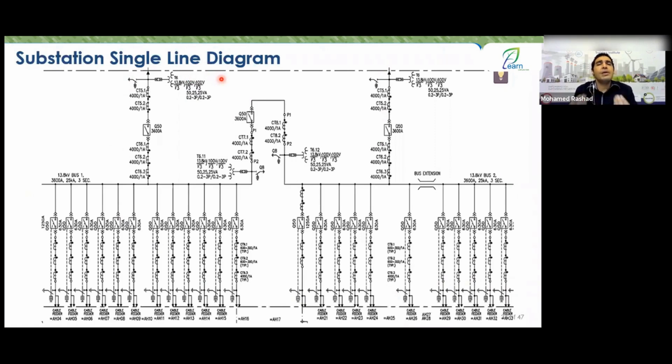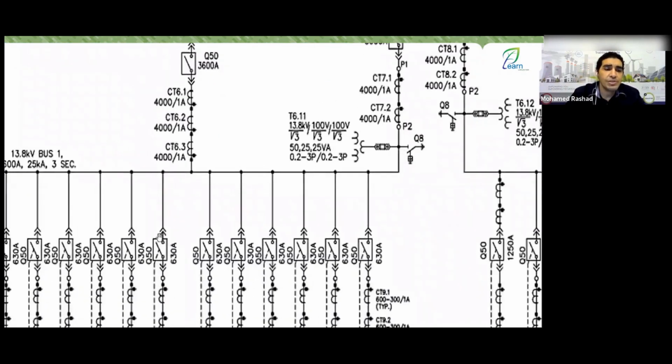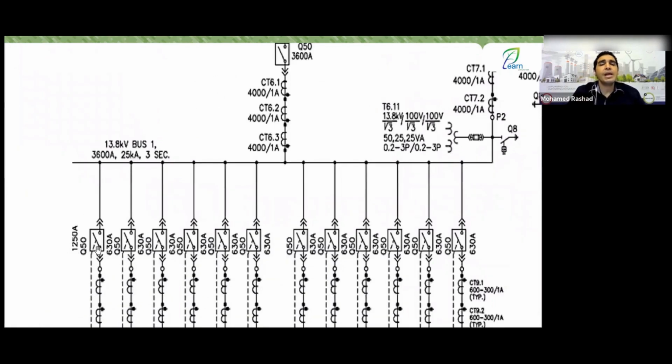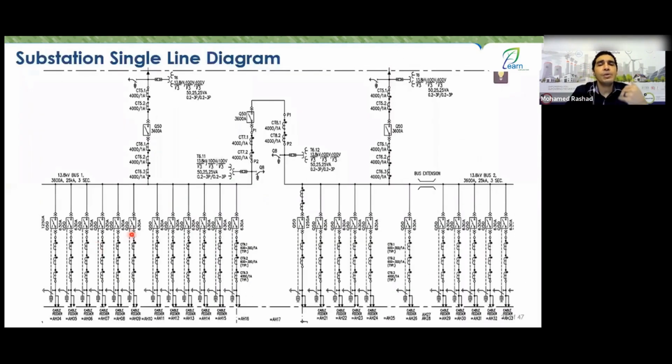And it's called a single line because our electricity, whether in generation, transmission, distribution, or even at your home, is three-phase. So you always see a bus bar as a single phase, you always see a breaker as a single phase, but in reality, it's three-phase. So here we call it a single line diagram, meaning I draw one line for you, any phase, and of course, they are all copy-paste for the other phases.